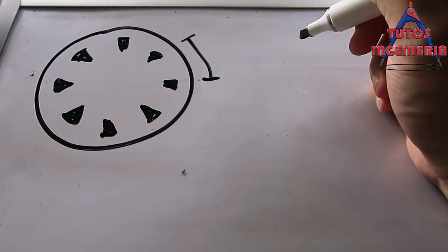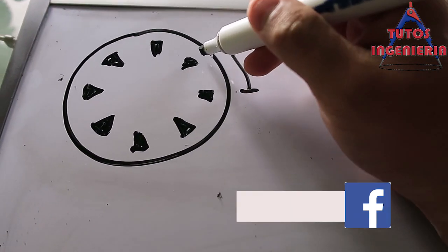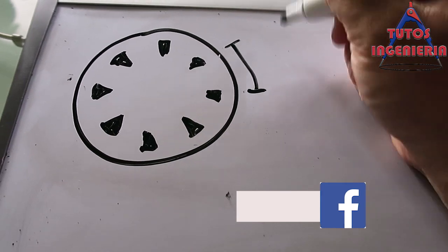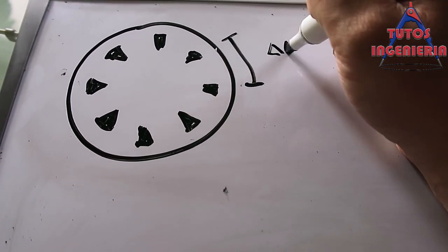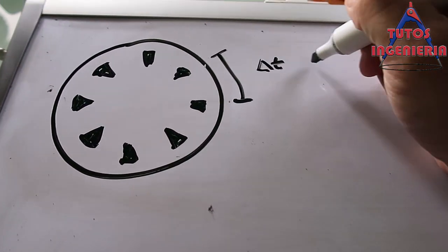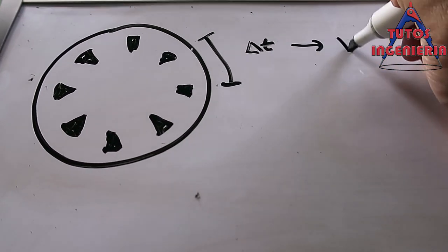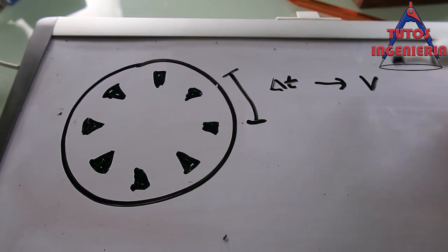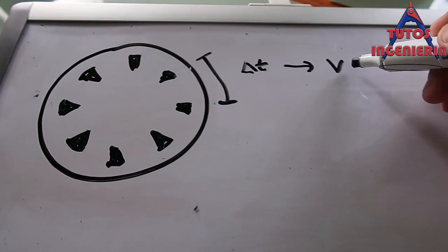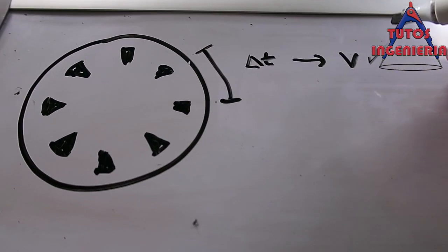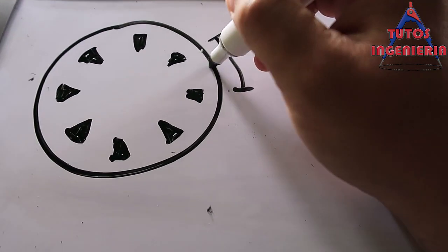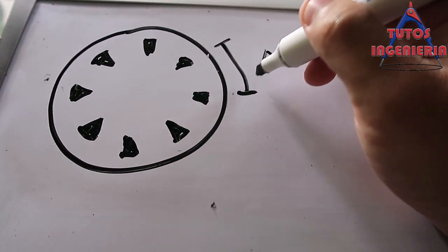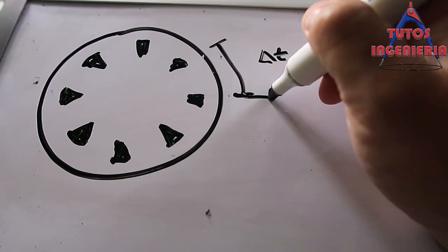I think that our calculation is based on the ticks. We calculate the delta time between ticks, and that generates our velocity, the speed of the wheels. So if the wheel stops, then it is a problem, because it waits for the next interruption.